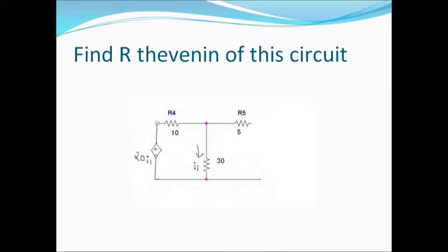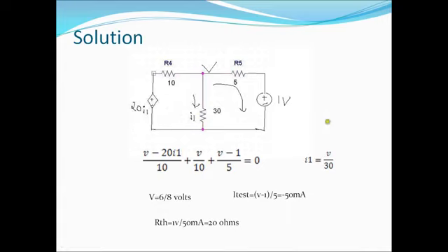In order to approach this circuit, to solve R Thevenin, we need to introduce a source that is called a test source. So again, here are the A and B terminals. Let's see how to solve this one. We have introduced 1 volt. This is the test source, this is I test, and this is voltage V. R Thevenin will be V test upon I test, because we need to find Thevenin's resistance across the terminals A and B.